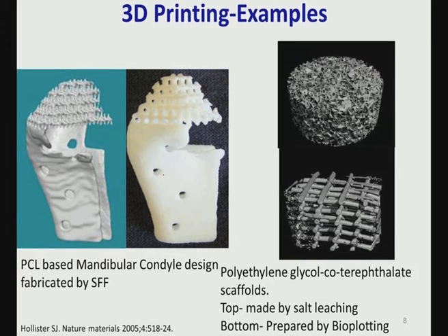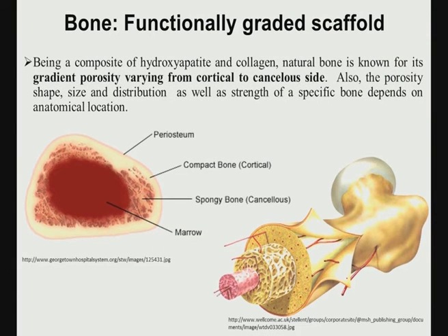Some examples of these 3D printed structures are polycaprolactone based mandibular condyle design fabricated by solid free form fabrication. SFF stands for solid free form fabrication. Also, PEG, polyethylene glycol based scaffolds, like salt leaching, are prepared by bioplotting.